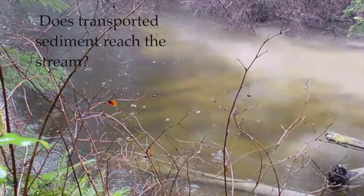Next, we look at if that sediment actually reaches a creek. You will find that lots of erosion products generated by roads will not reach a stream. Although losing fines may be damaging to the road surface itself and be of great importance for road trafficability, it really doesn't affect water quality. Fines generated by surface erosion but not able to be carried to a natural surface drainage do not contribute to water quality degradation.